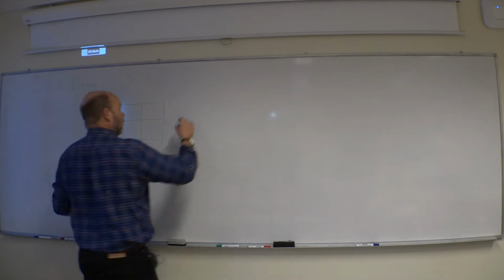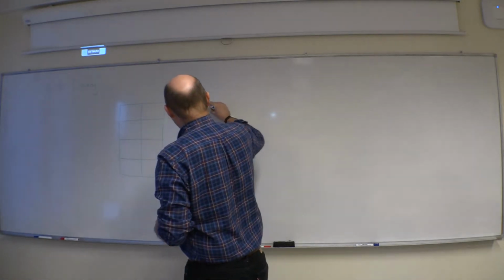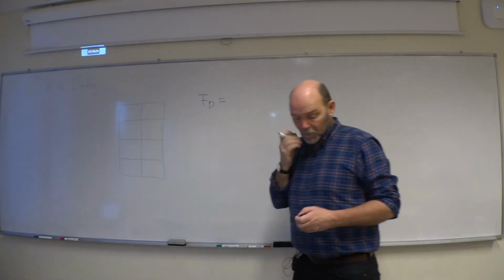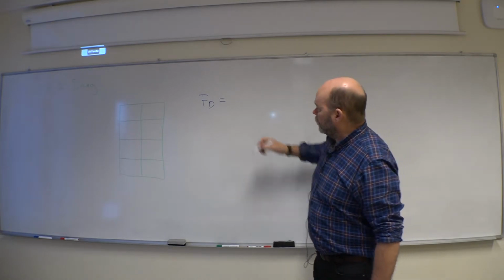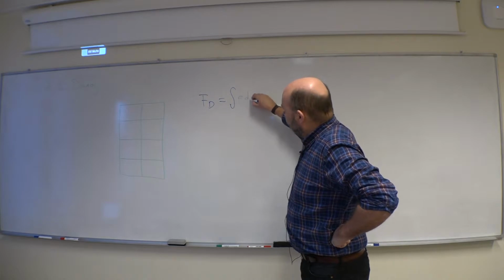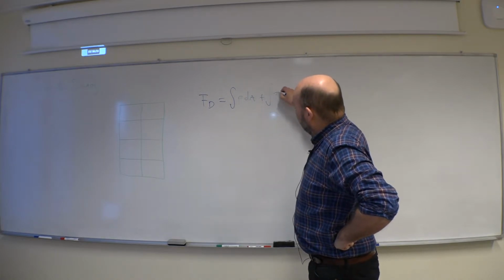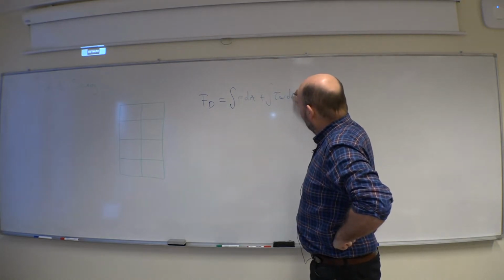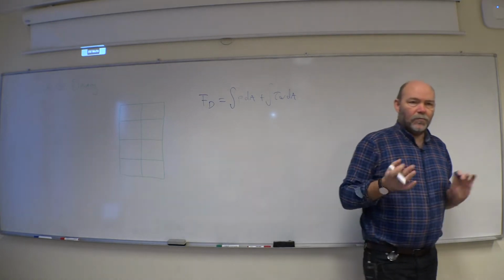So let's look at the drag first. How to find the drag force? Well, it's going to be an integral of the pressure and an integral of the wall shear stress. But the areas there will be different.